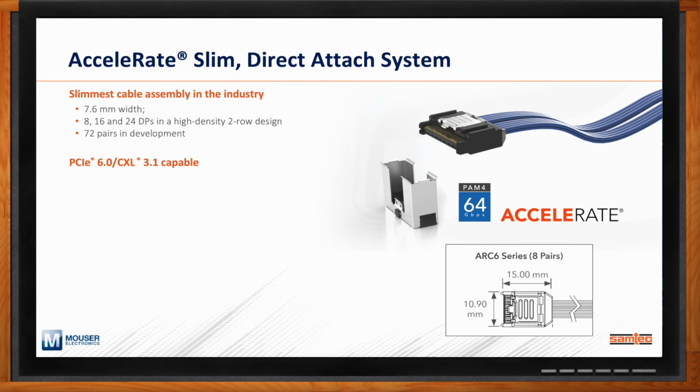So for Accelerate Slim direct attached system, it's a very small PCB mount connector, 7.6 millimeters wide. We can support 8, 16, or 24 differential pairs in a two-row design. We're also working to expand that up to 72 differential pairs within a single connector. Again, we mentioned earlier when talking about FlyOver technology, one of the benefits that Samtec has over the rest of the industry is the fact that we can directly attach the conductor from the Twinax cable to the contact on the connector body. So that eliminates a transition step on the connector assembly to increase performance.